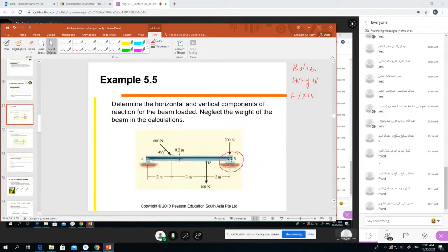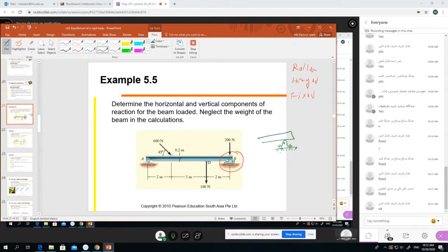As I have shown you in the graph, this is the hinge. Why hinge? You see, this is the nut bolt pin. This is the hinge. Usually, as I told you, the picture is drawn like this. Here is a bolt and here is a bolt, and they are fixed with the wall, and the beam is resting on it. So this is hinge support.